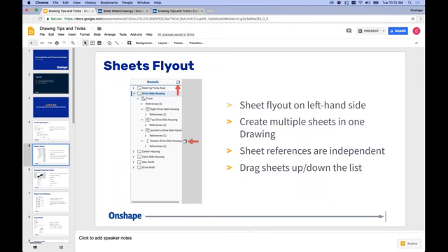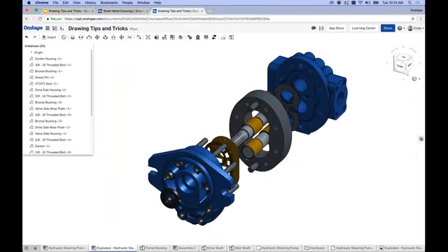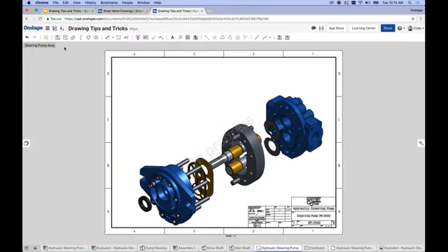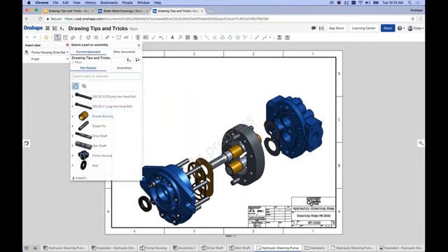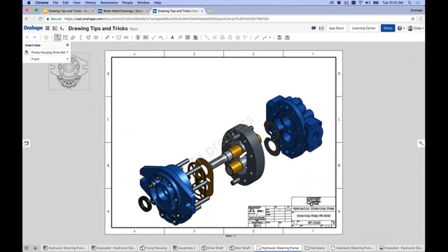Is there a way to introduce more than one part into the same drawing? Sure. In your insert dialog, you can go to insert another part, right? So if I go to insert, click the browse here, I can browse to another part studio and insert a view from a different part into this sheet. Sure. Right. More than one part, it could be an assembly and another part. It just depends on the scenario. But absolutely, just go back to the insert option, right? Insert dialog and choose the assembly.